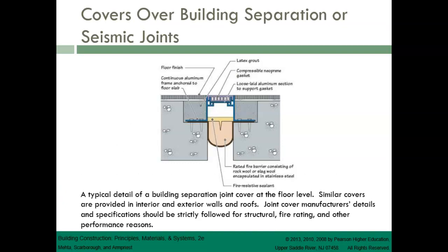This is a typical detail of a building separation joint cover at the floor level. Similar covers are provided in interior and exterior walls and roofs. Joint cover manufacturers' details and specifications should be strictly followed for structural, fire rating, and other performance reasons.